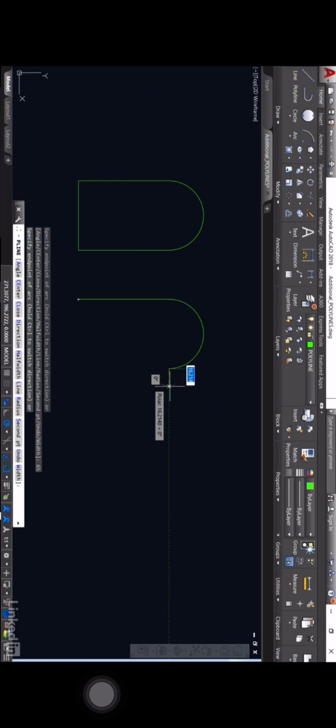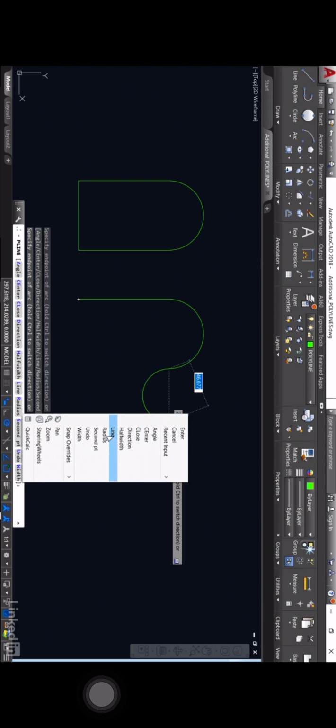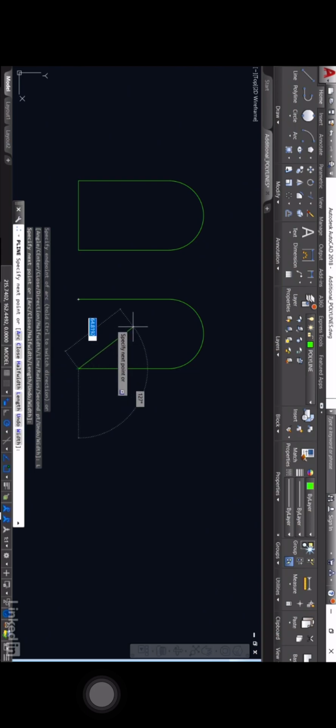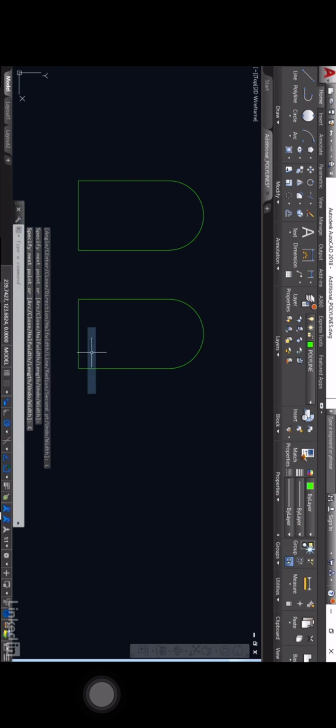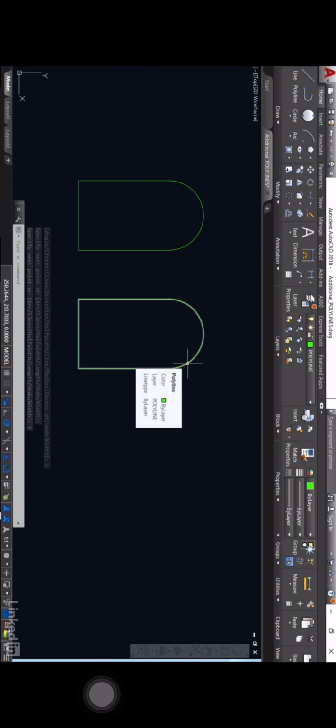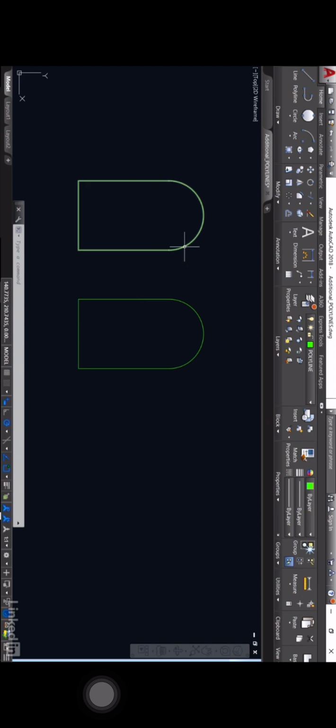And as you can see, it's drawn an arc, but now it tries to draw another arc segment, which I don't want. So I right click, I go to the line command part of the polyline command, and I'm back using a line segment. Now the good thing is I can utilize my object snap tracking now. I can hover there and I can hover there. Don't click, and then as I drag down, I get the intersection, click there, right click again, and close the polyline. And what I've done there is I've drawn a polyline that is exactly the same as this polyline.